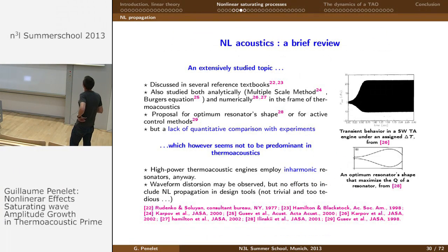Okay, so the problem of nonlinear propagation of acoustic waves has been very extensively studied in many fields of acoustics, and it has also been studied in the frame of thermoacoustic engines. So for instance, in this picture, you see a numerical modeling which presents the transient regime of wave amplitude growth in a standing wave engine with a stack which is submitted to a constant temperature gradient.